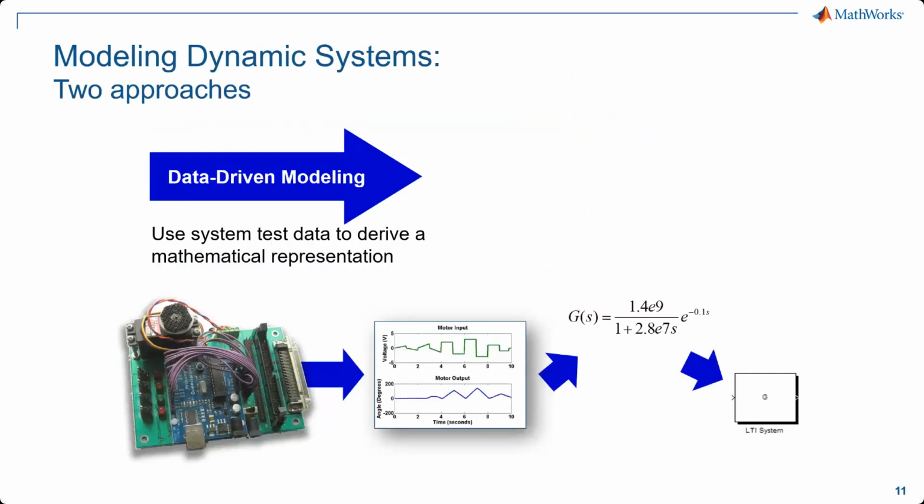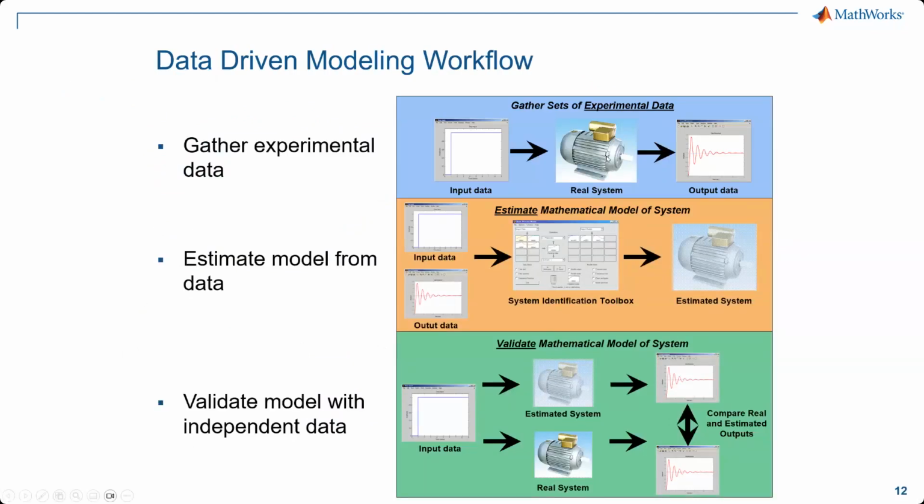So in modeling dynamic systems like motors, there are various approaches. The very first approach is called data-driven modeling. In data-driven modeling, basically we have a physical motor. We give certain input to that motor, and we capture what is the output, for example RPM, and take a log of it. For example, if I give input voltage from 0 to this volt, I will also record how the RPM is rotating, and then I will use that input and output data to find a transfer function.